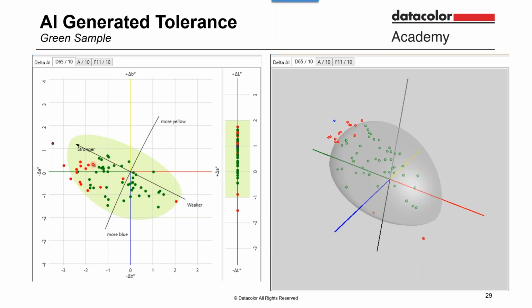You also should have pass and fail samples because it'll take into account both. In this case, you notice over here, the hue difference cuts down on the yellow, but there's not a lot of fail samples over here, so it's just assuming that these will be passed. So the fail samples are good, as you can see over here. The fail samples help define the ellipsoid.